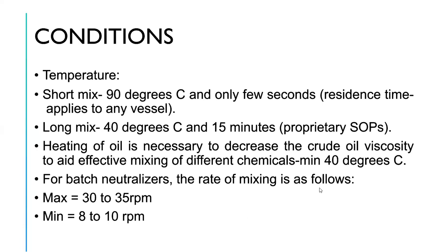For this one, there are proprietary standard operating procedures, which I will not talk about here for my company, which means the way these recipes are done, they differ from company to company. Some companies will heat up to 60, some to 80. Heating of oil is necessary to decrease the crude oil viscosity to aid effective mixing of different chemicals. So a minimum, it's 40 degrees Celsius.